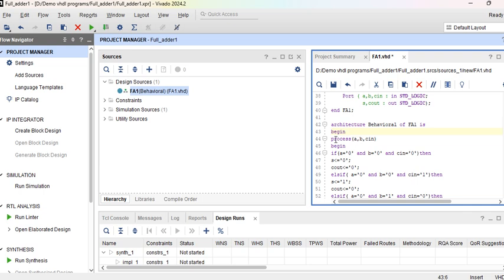And then begin. After this, we are beginning the process, and then here you can see the if else if ladder. The first if is the first line of the truth table, and whatever outputs we are getting, we are just assigning. Make sure that if a is equal to 0, the 0 should be in single quotes. Whenever you are assigning numerics, they should be in single quotes.